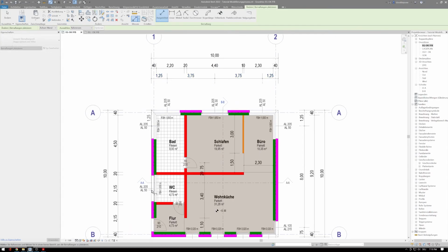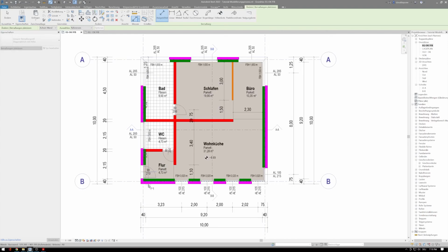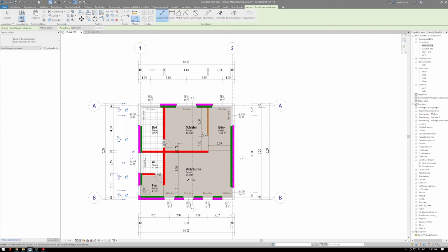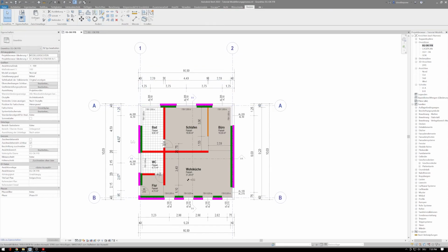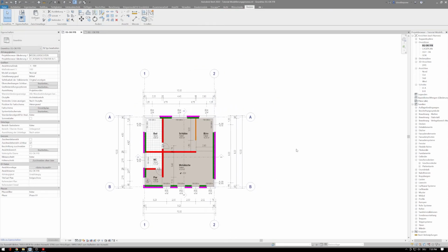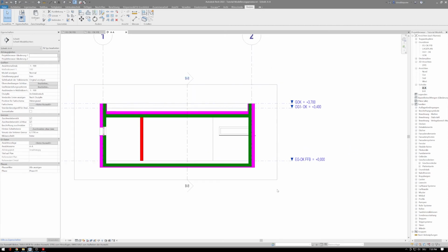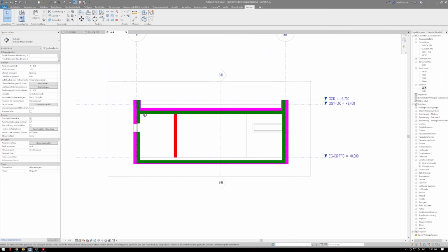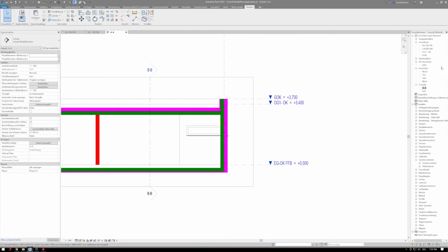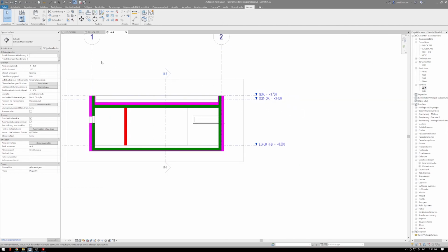I do it one more time. And it's done. I just move these a little bit inwards. Perfect. Let's go to our section views and start working on them. First things first, what I want to create is some different levels to annotate my section, but I don't want them to be active in my project browser. Well, how can I do that?